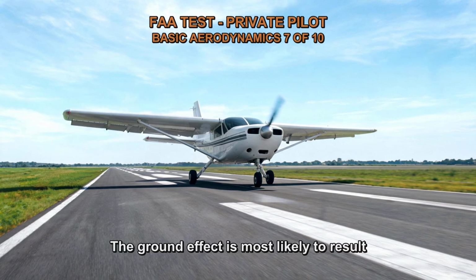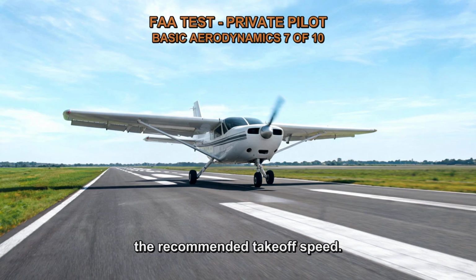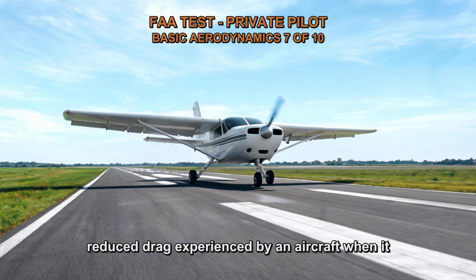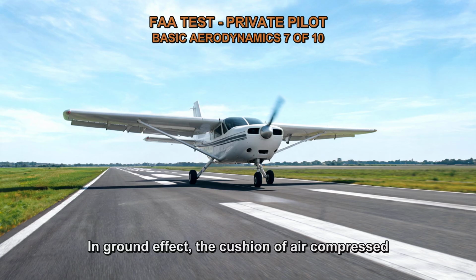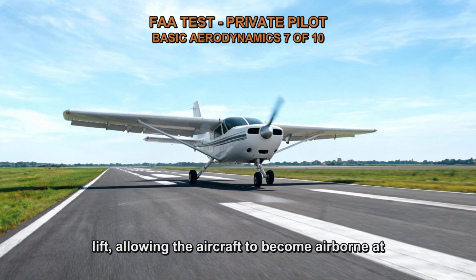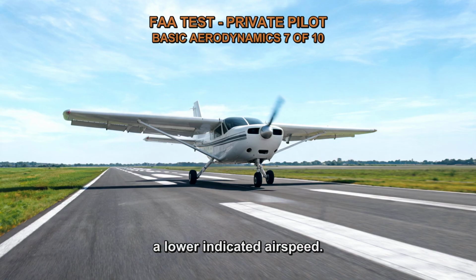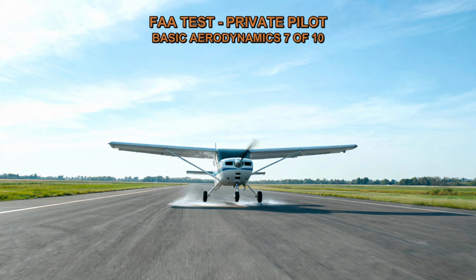Ground effect is most likely to result in the problem of becoming airborne before reaching the recommended takeoff speed. Ground effect refers to the increased lift and reduced drag experienced by an aircraft when it is in close proximity to the ground, typically within one wingspan. In ground effect, the cushion of air compressed between the wings and the ground creates additional lift, allowing the aircraft to become airborne at a lower indicated airspeed. This can lead to the aircraft lifting off prematurely, even before reaching the recommended takeoff speed.